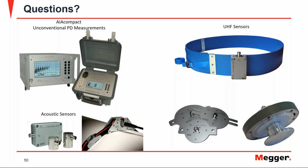However, what you can take into consideration is that a typical setup would be, for example, to have one UHF sensor on both sides of your circuit breaker, and then further sensors depending on the length of the GIB ducts that are connected to the GIS. So if you have a short cable exit right next to the GIS, then 2 to 3 sensors could be sufficient. If you have long GIB ducts, then you can have multiple additional sensors along these GIB tubes. So it's unfortunately something that can't be answered that clearly.